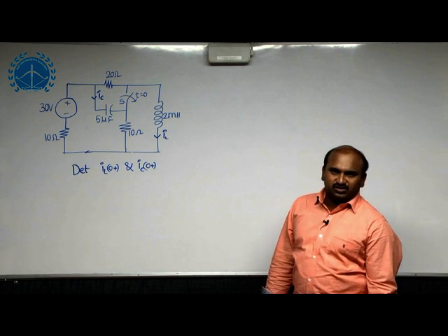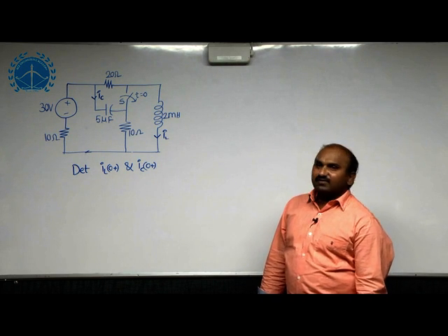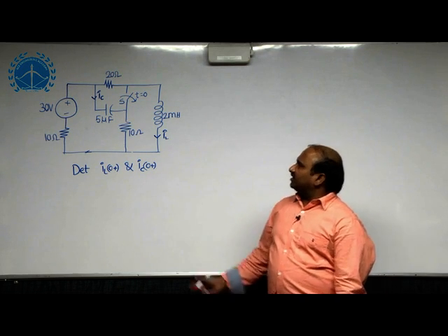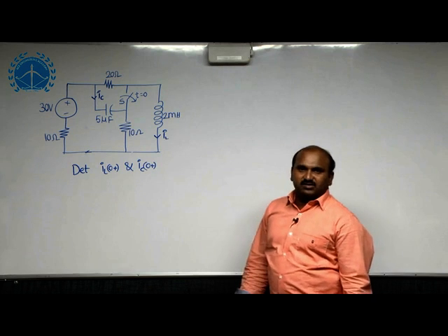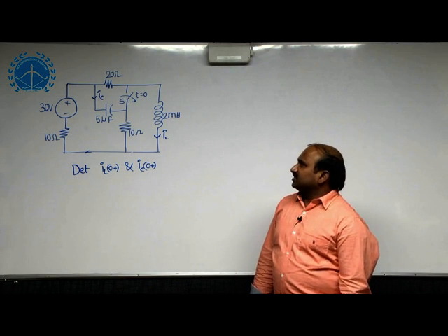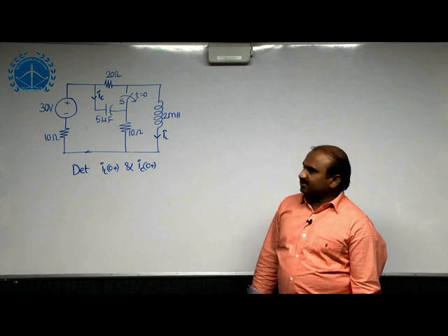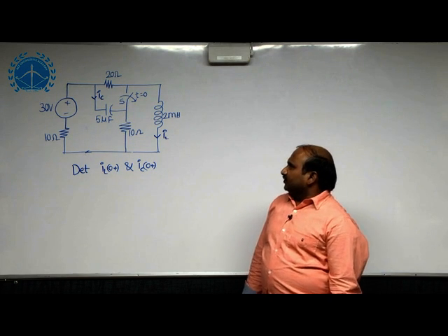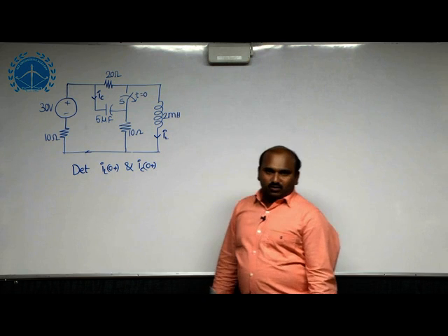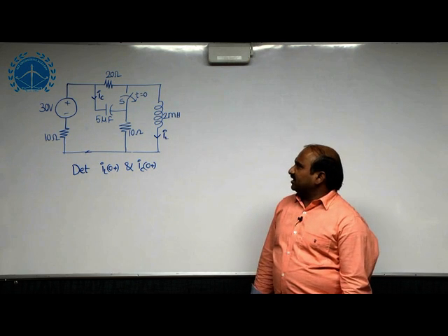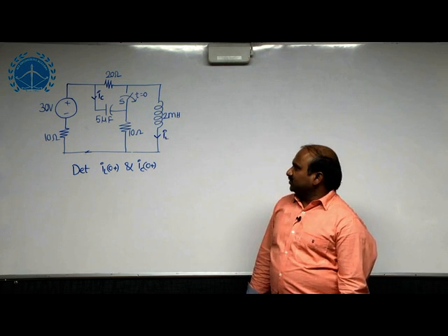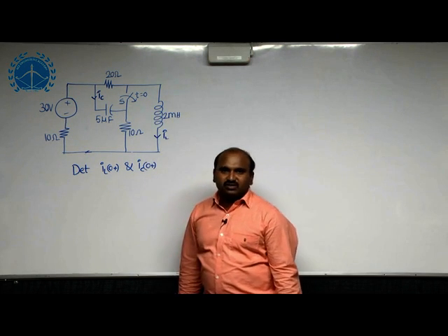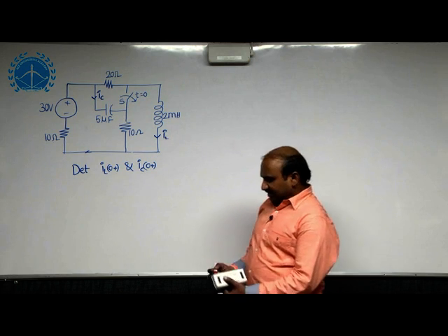Whenever the switching action is provided, transients will occur when the network is having energy storage elements. Now, in this network, inductor and capacitors are provided. That is why we are getting transient responses after t equal to 0, because sudden changes are provided by the effect of the switch. Now, we need to check whether the initial voltage and currents exist in the capacitor and inductor or not. We will get the initial values by considering the switching action before t equal to 0.